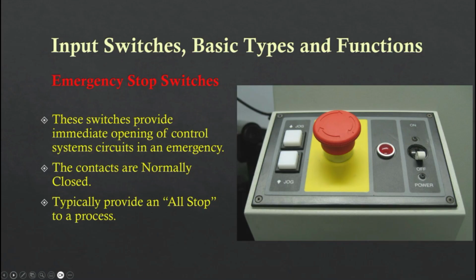Emergency stop switches. These switches provide immediate opening of a control system's circuits in an emergency, and the contacts are normally closed on an emergency stop. They typically provide an all stop to a process. That's hence the title emergency.